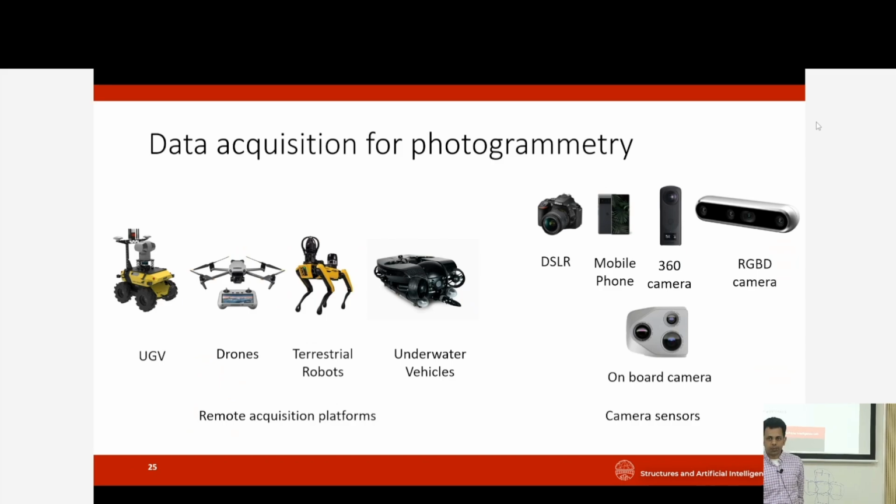So can photogrammetry be used for accurate surveying? It can be, but there's some caveats. You do need some sort of referencing, and typically that is done either with LiDAR or with some traditional surveying methods. So LiDAR is light detection and ranging.